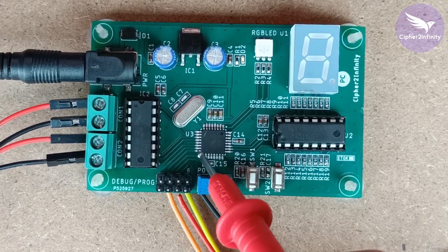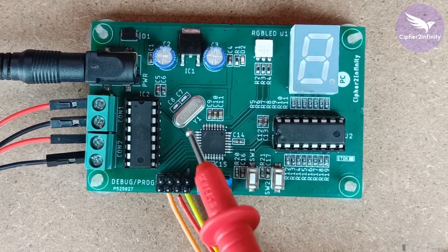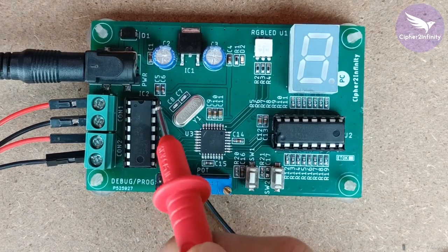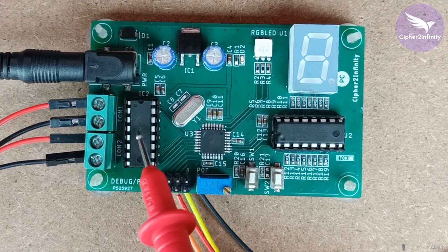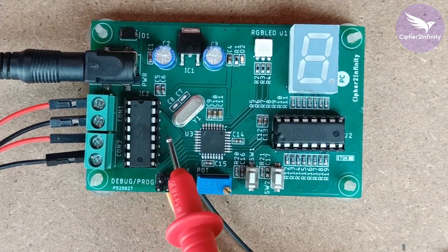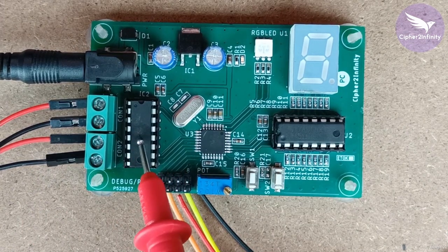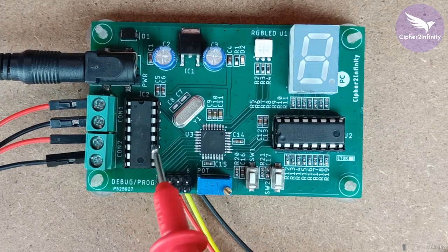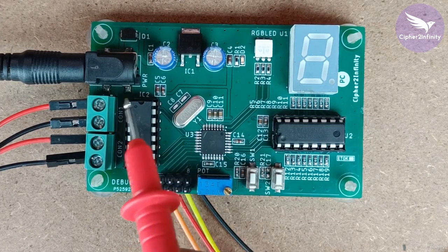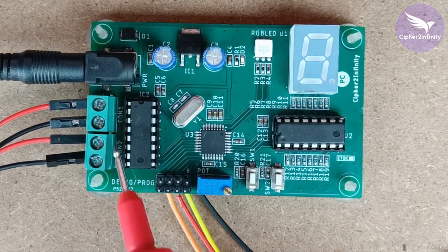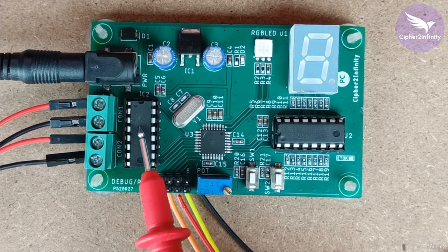And once you are sure that the controller is actually generating the appropriate voltage on the dedicated pin, then you have to check the same voltage on the pins of this L293D IC here. Okay, so you have to check the voltage on the control pin of the L293D, and even after that still, if the motors are not rotating, it means what? There is a problem with the IC. Okay, so you will have to replace the IC and you will have to insert the IC once again. So if you follow this testing and troubleshooting method in case of L293D IC, definitely you will find the issue and accordingly you can resolve the issue.